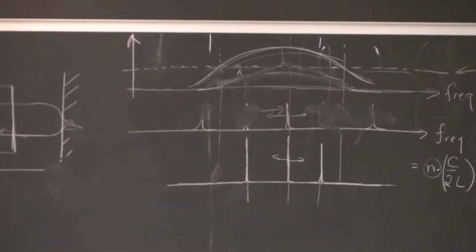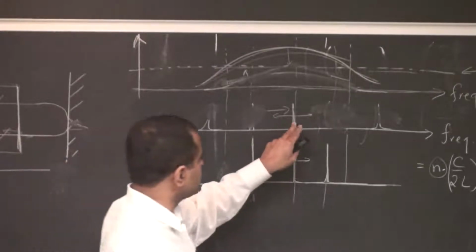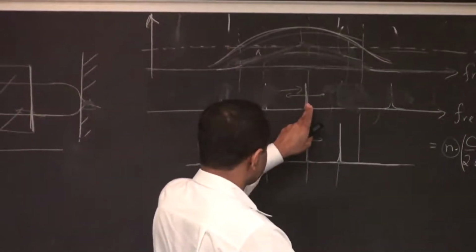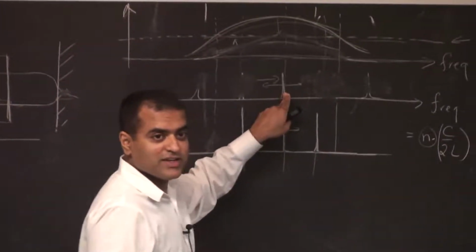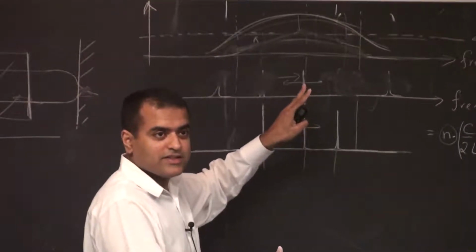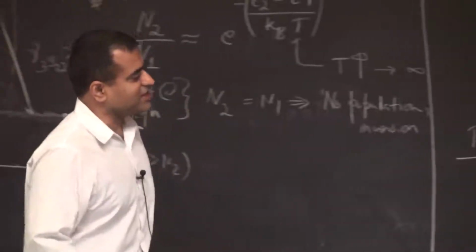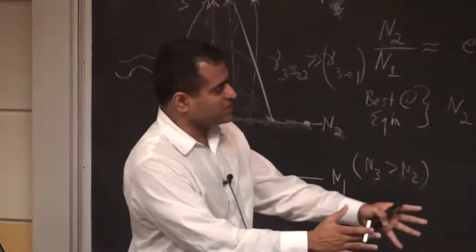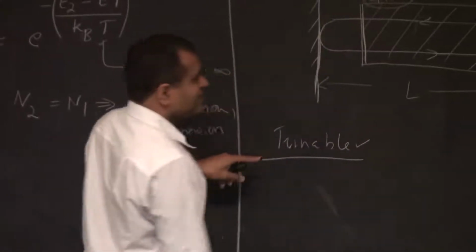And tunable lasers are very important because, as you know, you can transmit data or whatever at one frequency, 1.55 micron, maybe 1.53, 1.54. You can have multiple channels if you can tune it fast enough. Right? So, does that make sense? I mean, it's like different lanes in a highway. You can have different data rates going through different lanes. So tunability is very important and nice that you can do that.